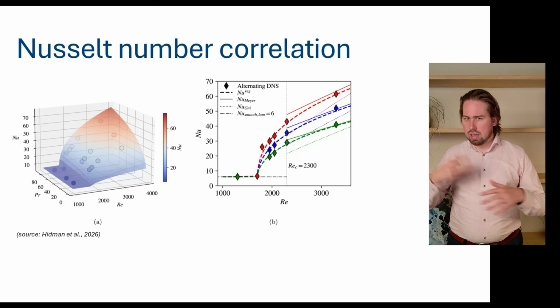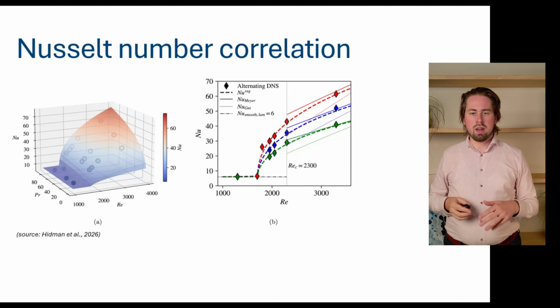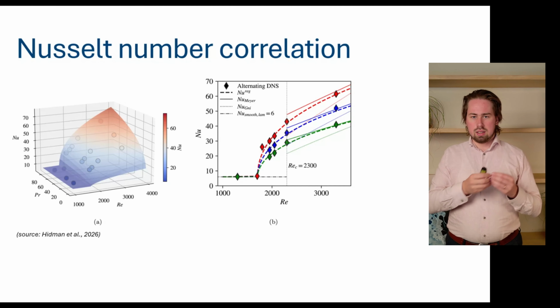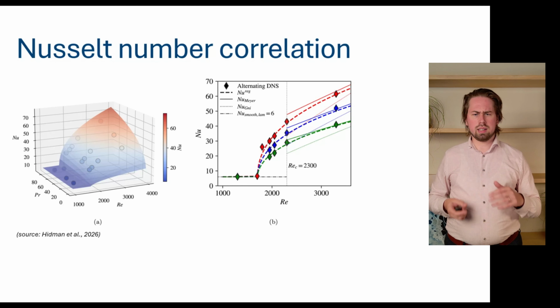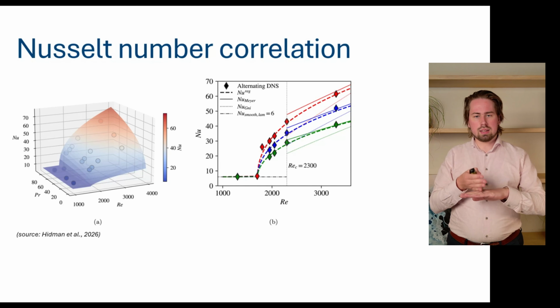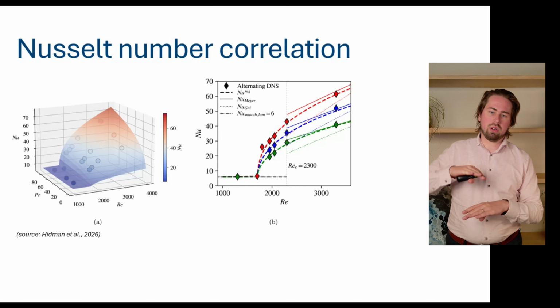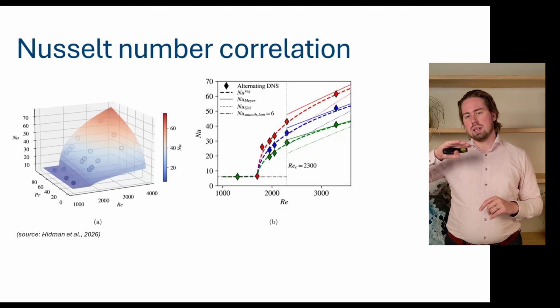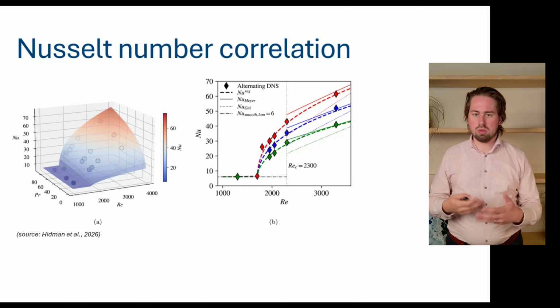So basically all the types of antifreezes are somewhere in this red to green range. And also here you see that the standard laminar Nusselt number, which is 6 in this simulation, and 3.66 analytically, deviates not at 2300 where you would expect it, but at 1700. It increases significantly, and then it converges to the Gnielinski correlations that are typically used to model turbulence in traditional smooth pipes.